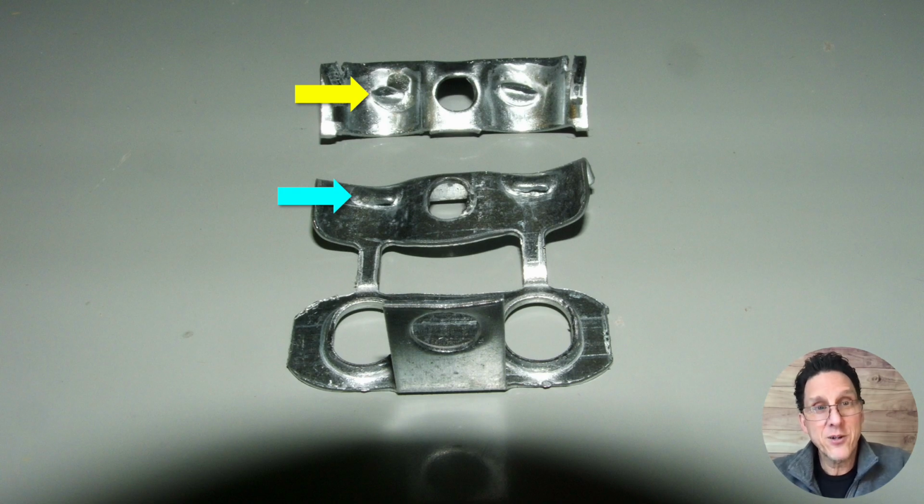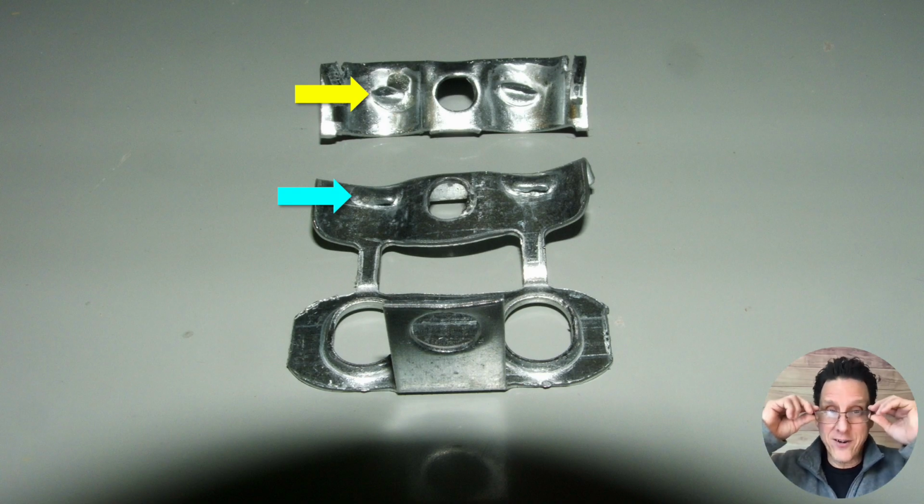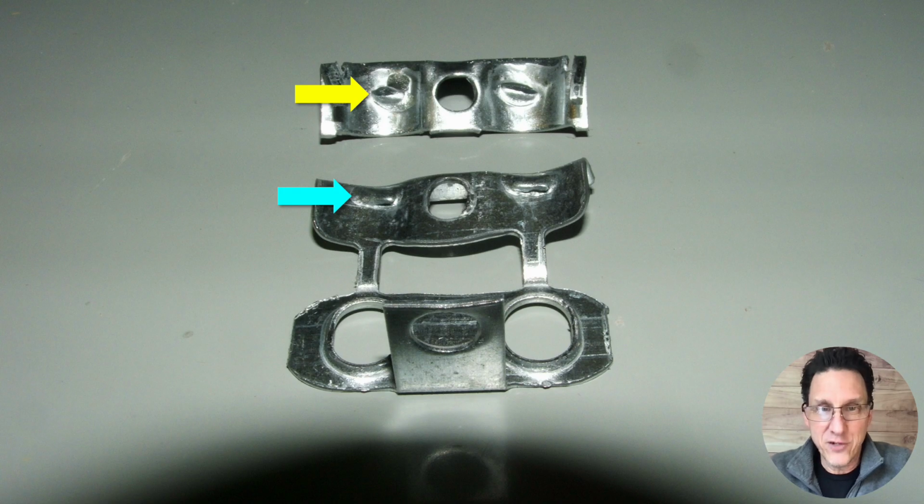Let's take a look at another clamp. And I've actually had to make repairs where people did just that. They used the wrong clamp, they tightened it down on an NM cable, and it ended up shorting out. Not right away, but like 4 or 5 or 6 hours later, and then I had to go fix that because eventually the breaker tripped. So that was a fun service call, or 2 or 3. Don't do that. Use the right clamp.